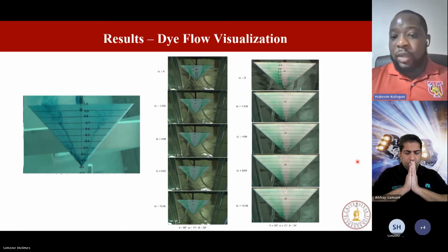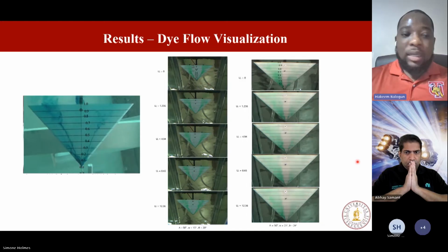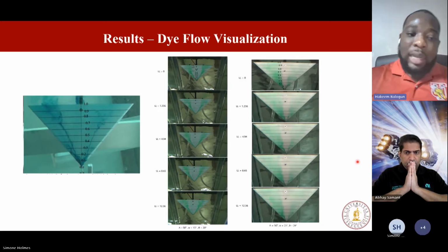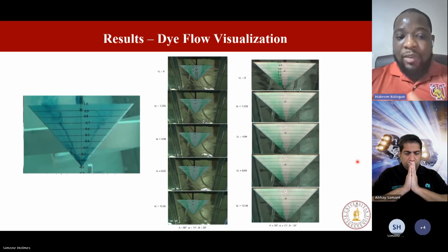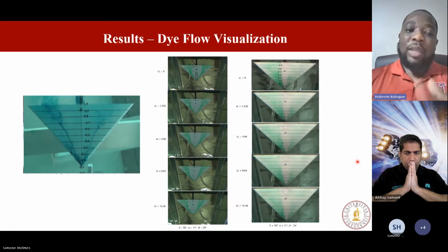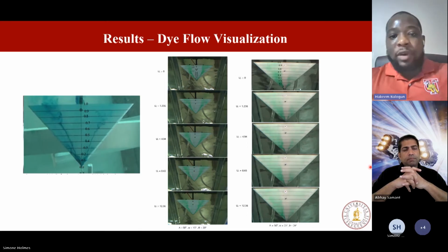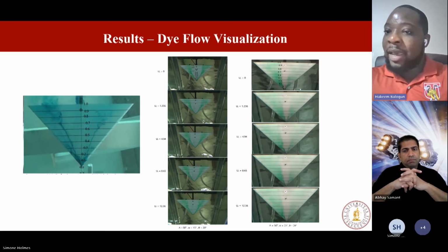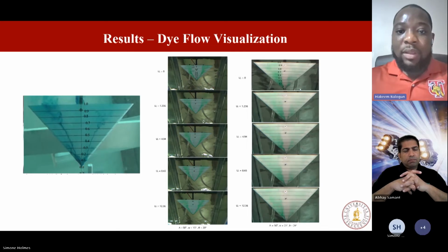With the introduction of trailing edge jets, the vortex breakdown location didn't noticeably change, but I noticed in my data that the rate of rotation about the vortex axis increased. So this is showing that the jet entrainment effect is still in effect, even though the vortex breakdown location might not move further back for this particular angle of attack. And this is important for the PIV data that I'll show later.